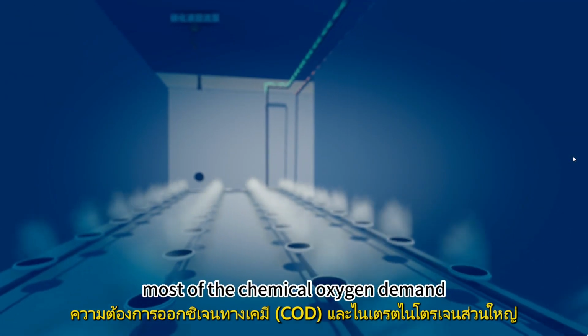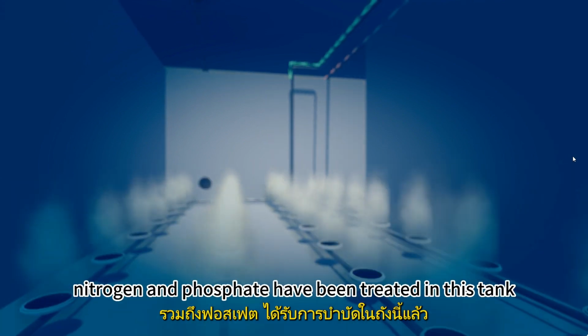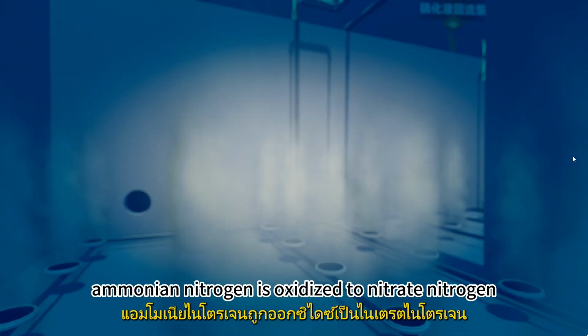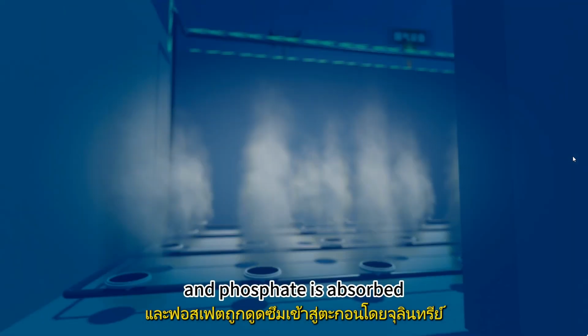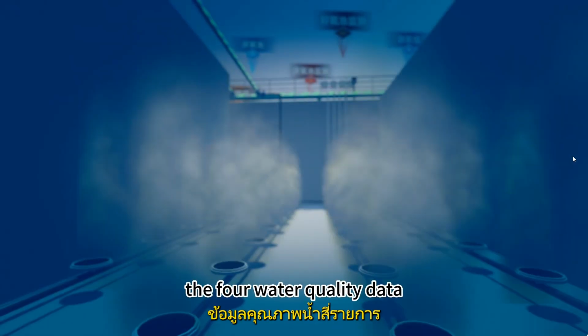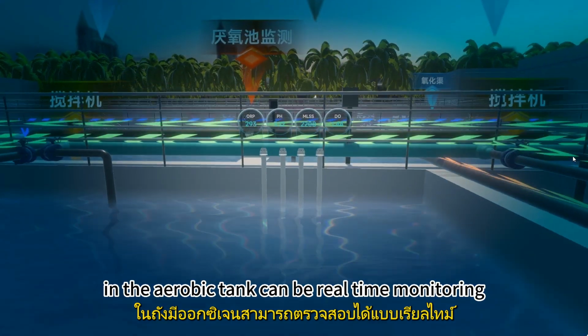Most of the chemical oxygen demand, ammonia nitrogen, and phosphate have been treated in this tank. Carbon is oxidized to carbon dioxide, ammonia nitrogen is oxidized to nitrate nitrogen, and phosphate is absorbed into the sludge by microorganisms. The four water quality data in the aerobic tank can be monitored in real time.